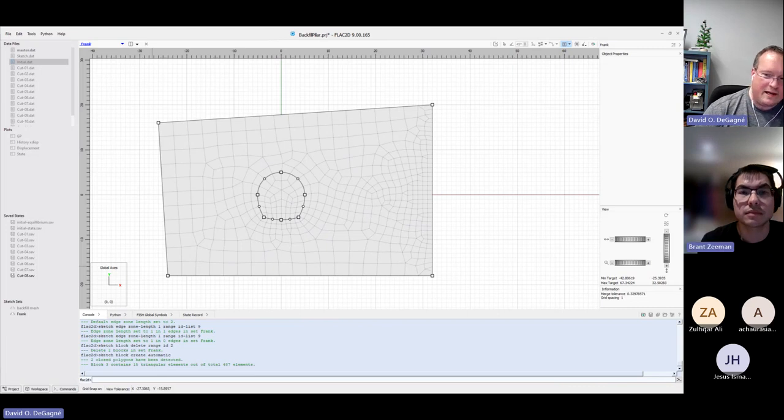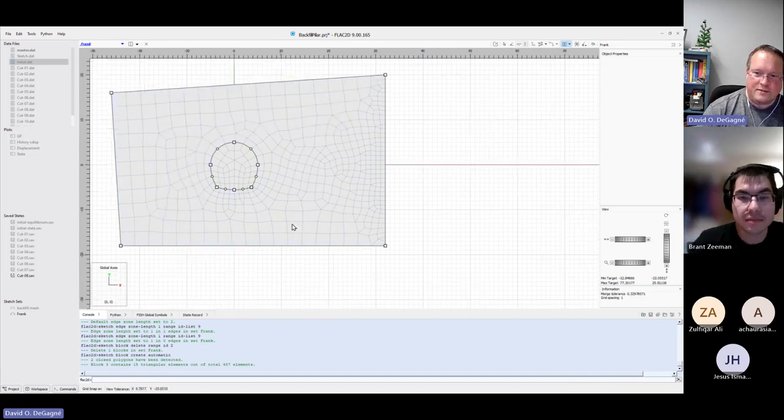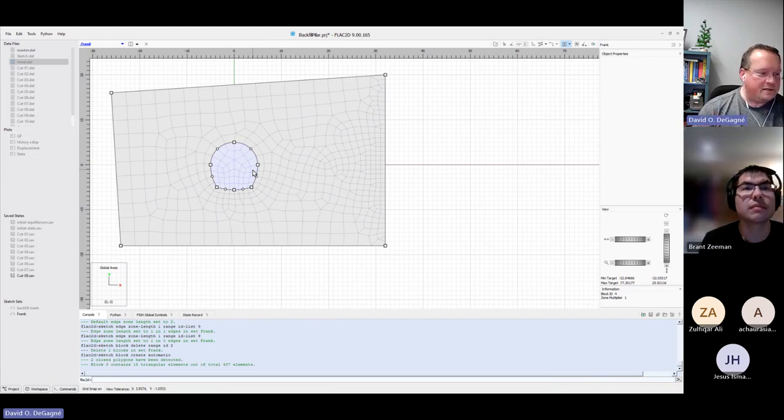And the model's kind of like that in the sense that if we just instantly say this tunnel was a kilometer deep, and so we've got really high stresses around here, and then we just took that tunnel out, then all of a sudden, instantaneously, within the first few steps, the boundary of that tunnel would want to push in. And it might do it at a rate that's not realistic. But in fact, it would almost certainly do it at a rate that depends on the strength of the material.